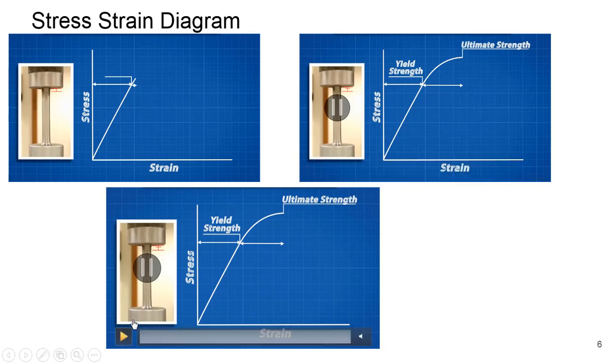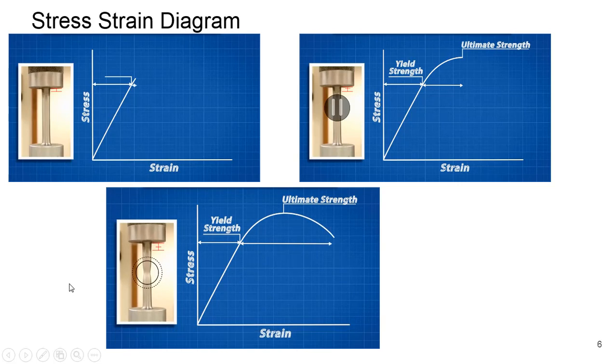Okay. Now finally we will see the last part, during which necking occurs. That means where the fracture is going to take place, suddenly the area reduction rate increases at a very high rate. As you can see, look carefully at the diagram as well as the actual specimen, you see the neck formation and finally fracture takes place.